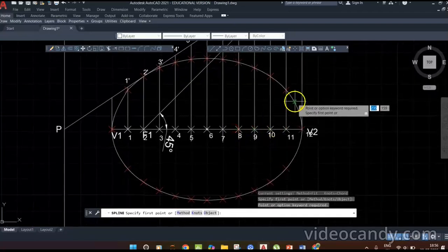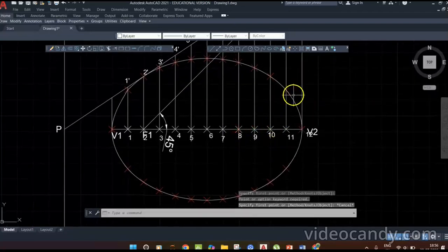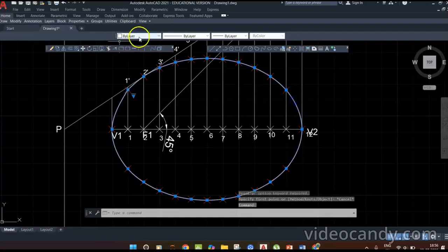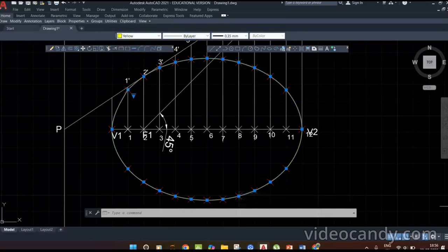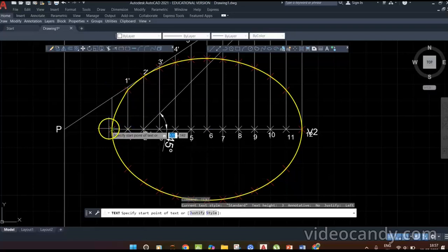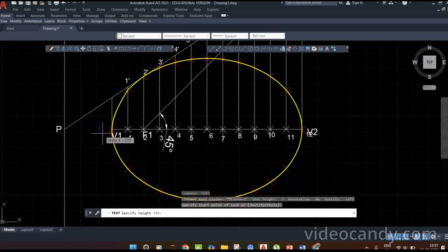This is the ellipse. So select that curve, change the color, apply the line thickness, make sure that line weight is on. Okay. On the periphery, red points are the locus points. Mark points on the curve by using the command text. This is my start point, P0.